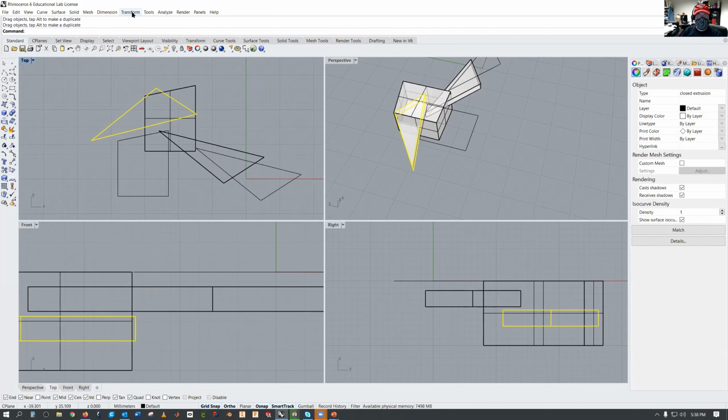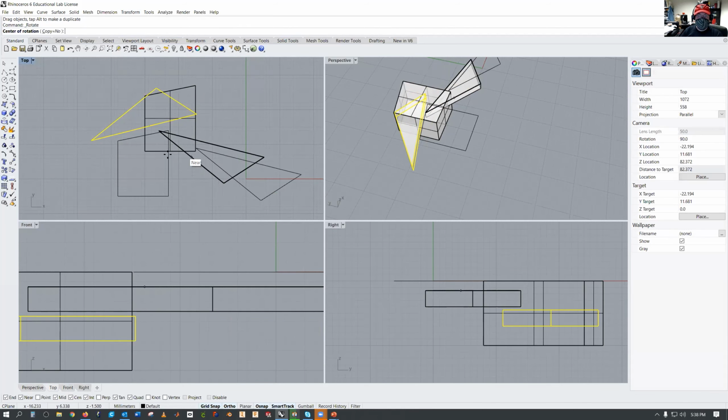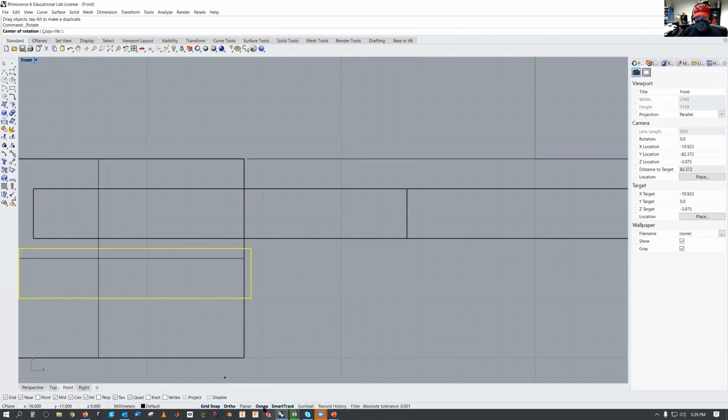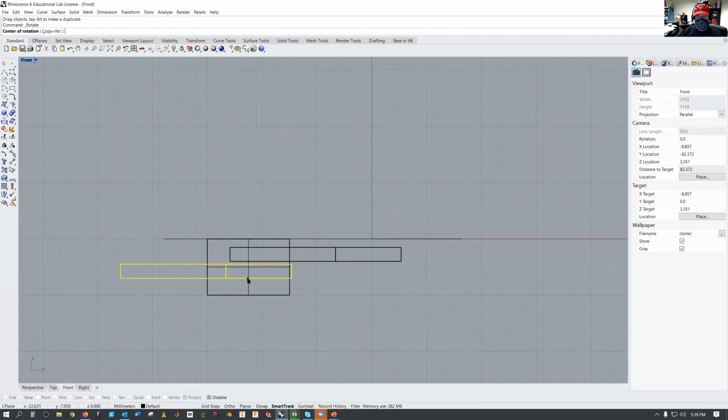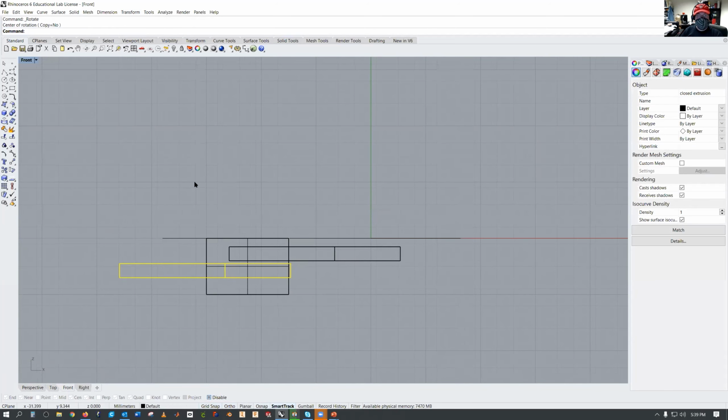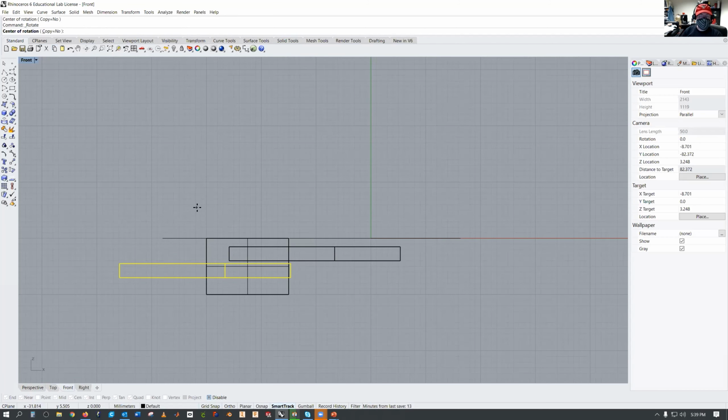Now you can also transform rotate. So let's say I'm going to turn off grid snap and ortho here. Okay, so I clicked somewhere else. I unselected my command of rotate. So now I'll just right click and it redoes it. It redoes the command that you were doing before.